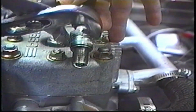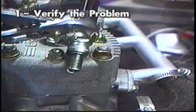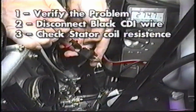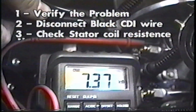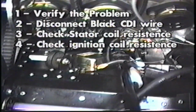When diagnosing ignition-related problems, follow a step-by-step diagnostic approach. First, verify the problem. Second, disconnect the black CDI wire, engine stop wire, and check all connections. Third, check the resistance of the stator coils. Fourth, check the resistance of the ignition coils. And fifth, check or change the CDI module.